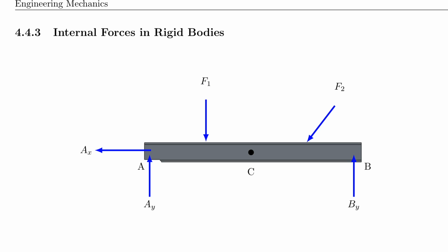And then the first thing we do, and the things that you've done in your last 3 homework assignments, were to find the external forces that are not given. So the support reaction at A and the support reaction at B. And you will have to continue to do that for each upcoming problem now. This is really the first thing you have to do, and that's why it's so important that you're so proficient at finding support reactions, because the support reactions define the internal forces. And if you do not get the support reactions correctly, then you cannot find the internal forces correctly, in this case at location C.